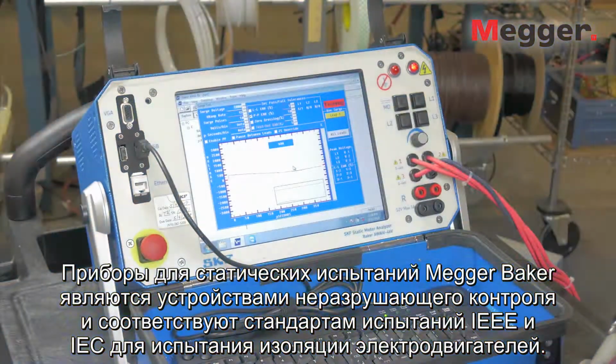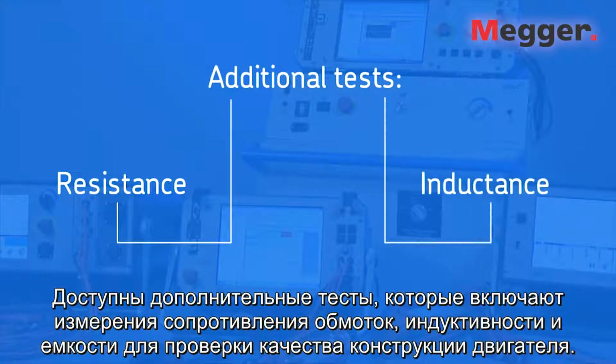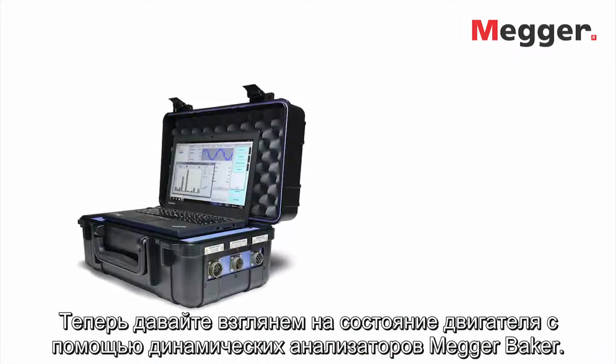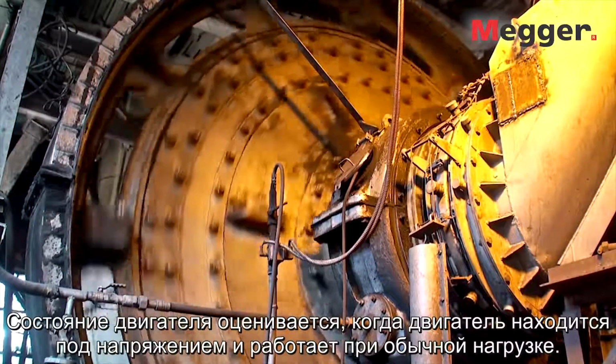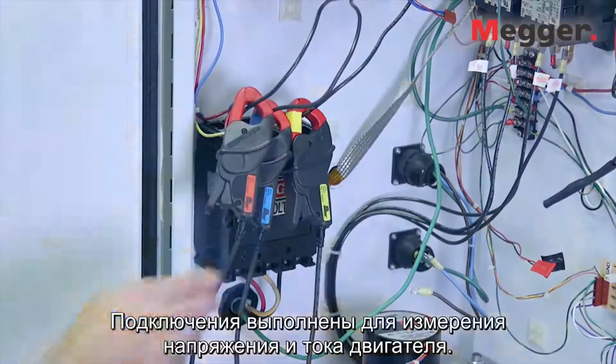Baker Instruments static motor tests are non-destructive and follow IEEE and IEC motor testing standards for motor insulation testing. Additional tests available include resistance, inductance, and capacitance for verification of motor winding construction. Now let's look at the motor operating point using Baker dynamic motor analyzers. The operating point is measured while the motor or machine is energized and operating. Connections are made to measure the motor voltages and currents.